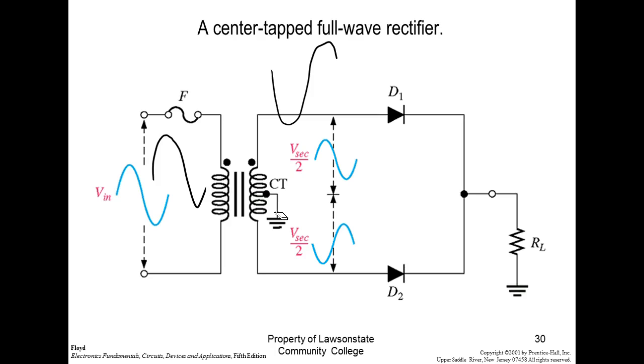Now, a while ago I was not utilizing the center tap. So I could do a half-wave rectifier without a center tap transformer. In fact, odds are that's what you're going to do, because when they have to stick that other wire in there, it adds cost to the transformer. So center tap transformers cost more than untapped transformers. We're using center tap transformers because it serves all the power supplies that we need to make, right? You understand that? But we don't have to use it. Here, you have to use the center tap. You have to use it. So a center tap full wave rectifier requires a center tap transformer.